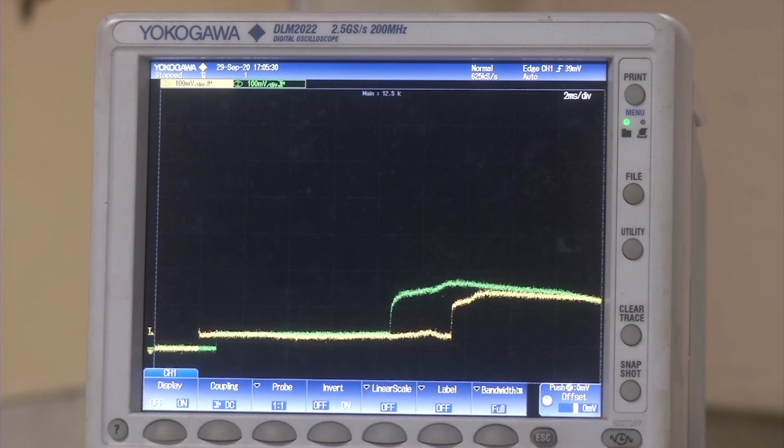But at the outset, what we are going to demonstrate in this event is that using the shock tube and the pressure transducers, we are capturing the pressure jump across the primary shock, which is seen as the first jump for pressure transducer 1, and also a similar pressure jump across the reflected shock. Both the pressure transducers show a significant rise in the pressure across the shock wave.